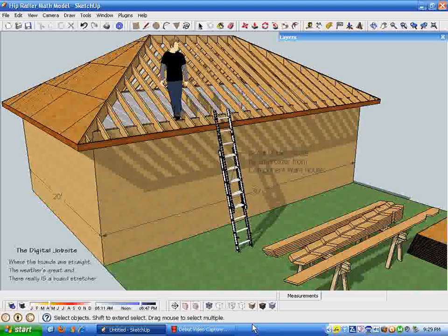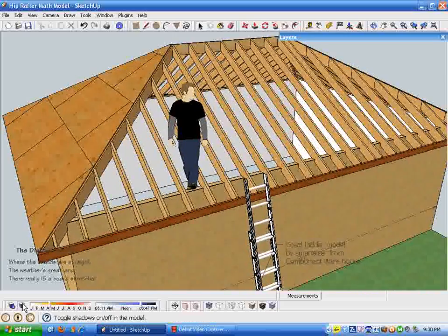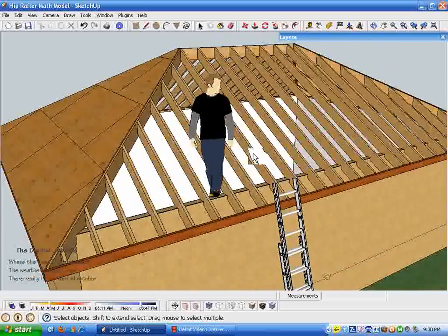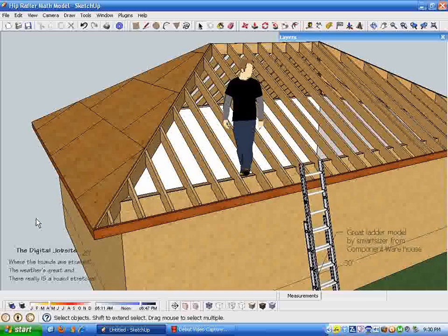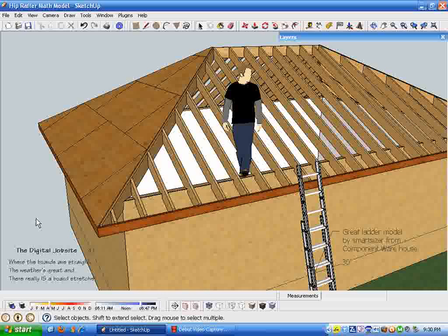And for those of you that are following along, part one was demystifying hip roofs by visualizing in SketchUp, and in that video I showed the how and why of the way that various components that make up a hip roof are cut and assembled to create flat roof planes that intersect in straight lines on the hip rafters. And then part two was demystifying hip roofs by modeling in SketchUp, where I showed how to model the various components and rafters that make up a model like this hip roof. And I did it in a 7/12 pitch just for a standard reference, but all the information in this series is intended to be structured so you can use it for any pitch that you might encounter framing a roof.